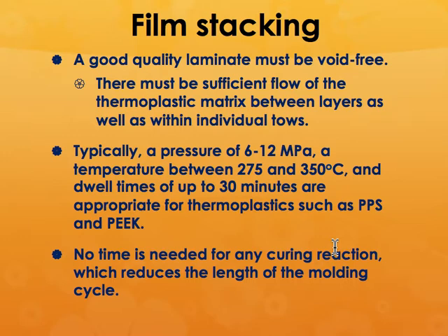Now, remember that for thermosets, the maximum processing temperature is typically 350 degrees Fahrenheit. And unless you are using things like polyimide or BMI and things like that, this processing temperature is not going to be higher than 350 degrees Fahrenheit. Okay, so thermoplastic composites are typical with matrices such as polyphenyl sulfone and polyaryl ether ketone.